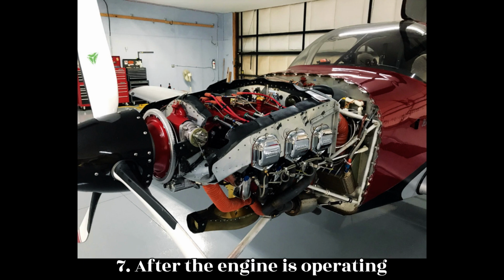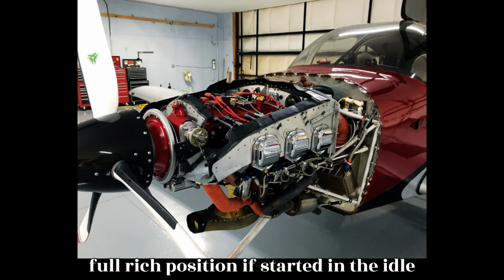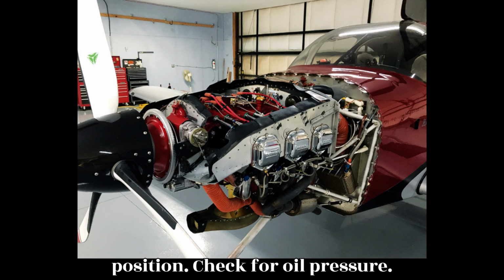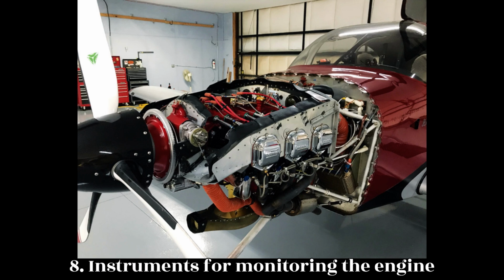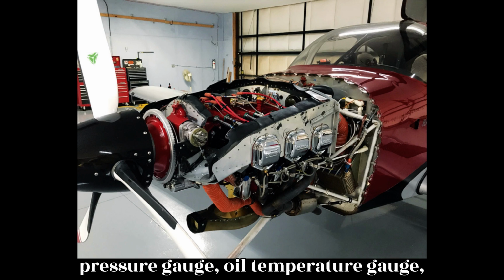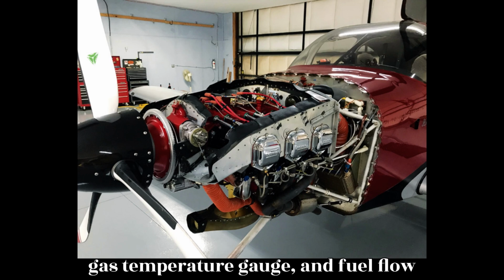7. After the engine is operating smoothly, move the mixture control to the full rich position if started in the idle cutoff position. Carbureted engines are already in the rich mixture position. Check for oil pressure. 8. Instruments for monitoring the engine during operation include a tachometer for RPM, manifold pressure gauge, oil temperature gauge, cylinder head temperature gauge, exhaust gas temperature gauge, and fuel flow gauge.